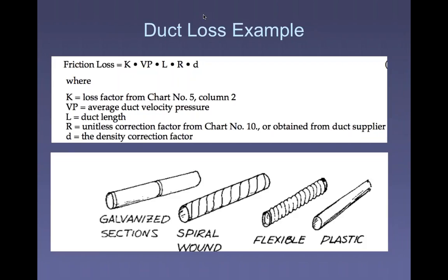We stuck with a roughness of 1 when we talked about ductwork, and we're going to continue tonight with a roughness of 1, which is typical galvanized iron ductwork. If we're using a rougher duct, like flex duct, that roughness factor is going to come into our equation. We're going to have to adjust our losses for something that's not a smooth surface inside the ductwork, because it's going to create more resistance.